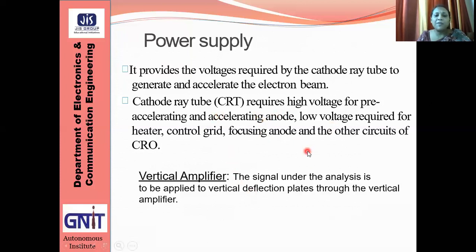So the vertical amplifier is the next section. The signal under analysis is to be applied to the vertical deflection plates through the vertical amplifier, so that it can be amplified properly and we can have the proper signal at the output.